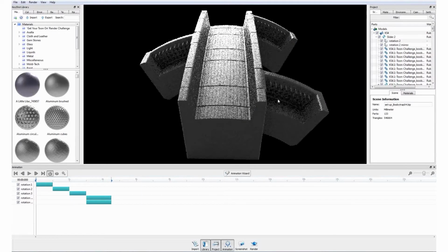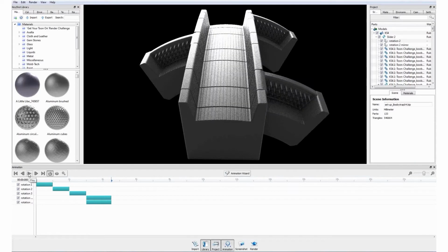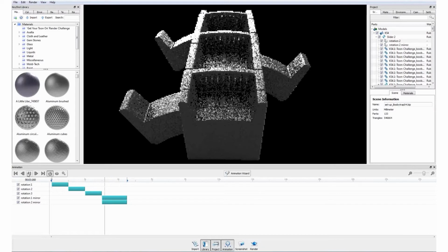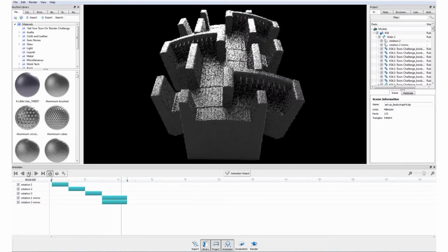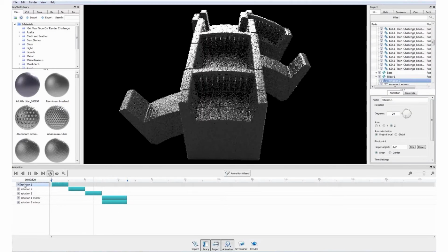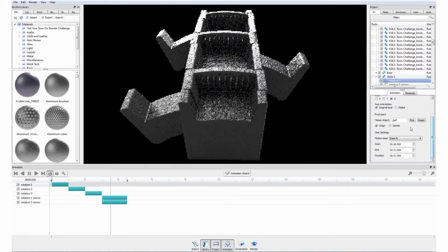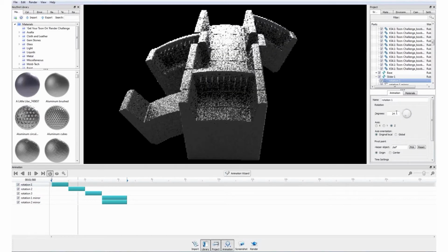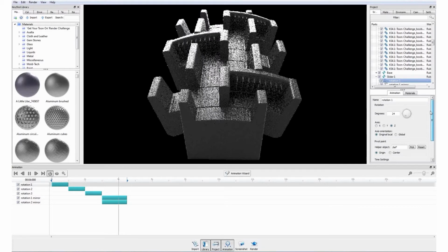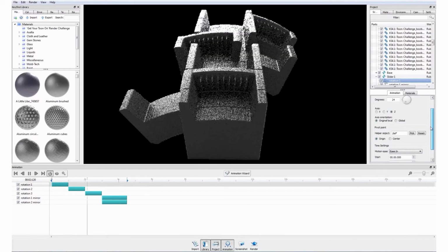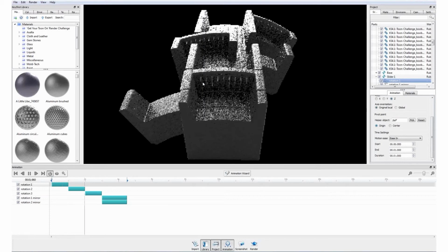So I set up the animations that I wanted to apply to the individual sections. These are all animations that I simply applied, set the correct axis, set the right degrees that I got from my CAD software, obviously, and just put the pivot point in a region, and it behaves just as I intended in CAD.